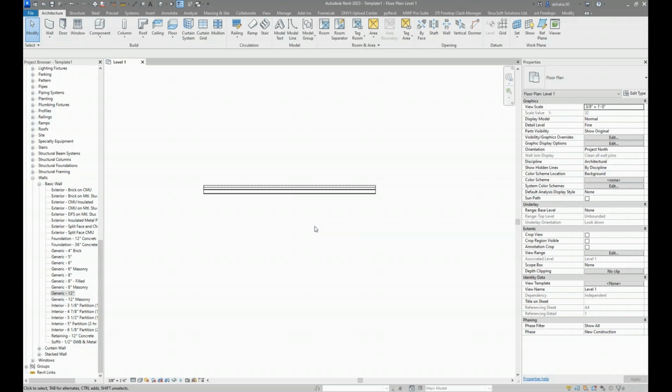I need wall types that have 3/5/8 structural layer with sheathing on one side, with sheathing on both sides, with sheathing and gyp on one side. All of those, you collect all of those in one area. So in one template, you'll collect all of those different things, so that in the future, when you have to use it, you just have to use it. You don't have to go insert it again, modify it, and see if it frames properly and all that stuff.